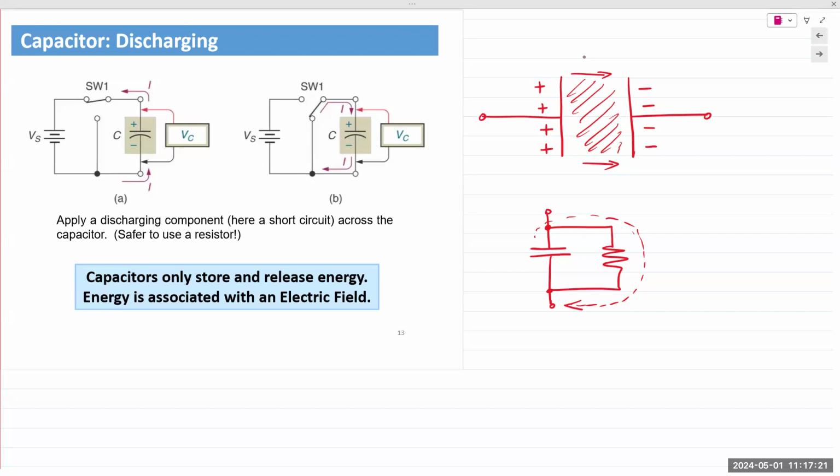Anyway, coming back to our topic under consideration, capacitor stored energy is finite. So you short circuit the lead, you might see a small spark. If you do this to a battery, which has much more stored energy than a capacitor, it'll lead to an explosion. So it's always safer to use a resistor to discharge a stored capacitor.